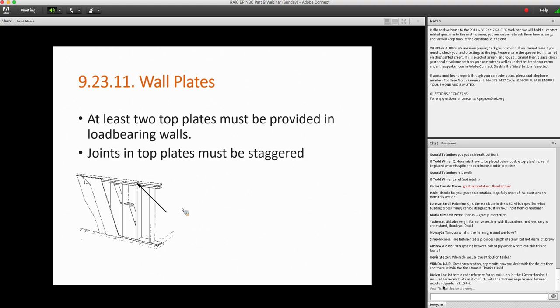I know under the CSA 086 standard, the screws for wood screws are defined, and because the National Building Code does point people towards that, I would guess that we should probably look at CSA 086 to confirm the screw diameter if it's not specified here, and I agree, I don't see it there. This is a new table for the 2015 version.